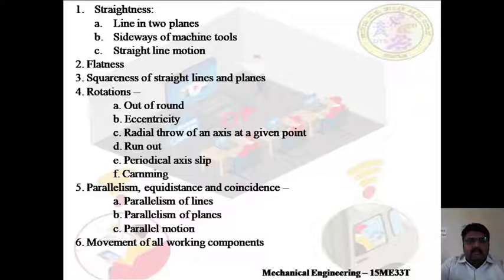And under parallelism, equidistance and coincidence testing, it is tested for parallelism of lines, parallelism of planes and parallel motion. So these are all different geometrical tests which are conducted on a machine tool.